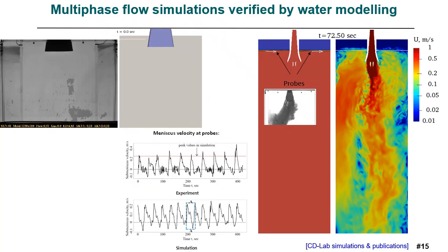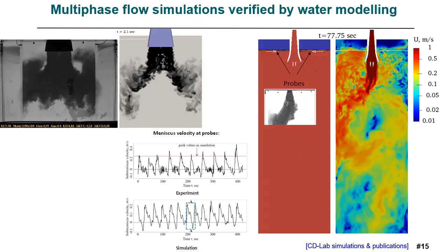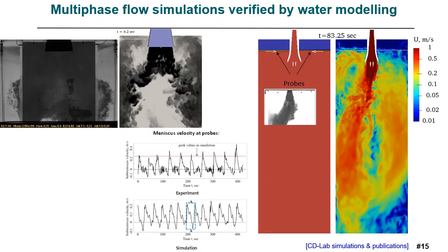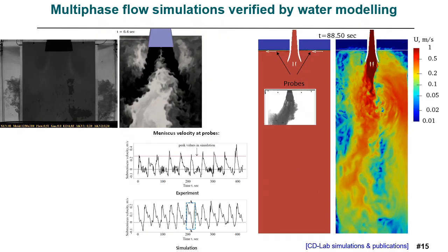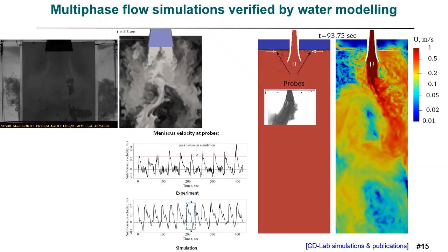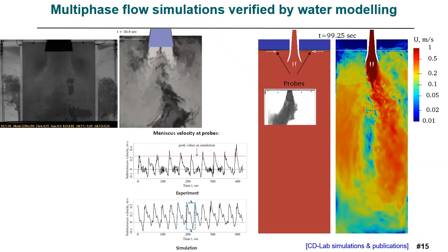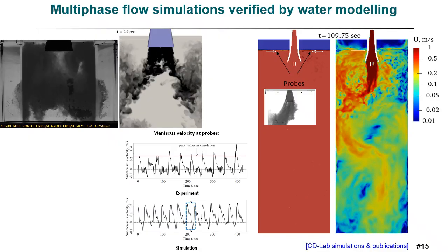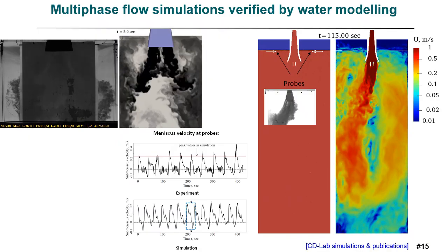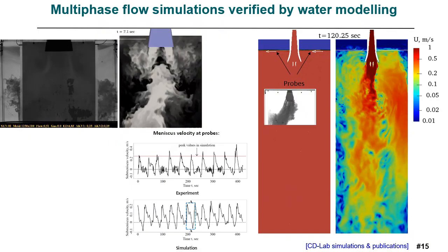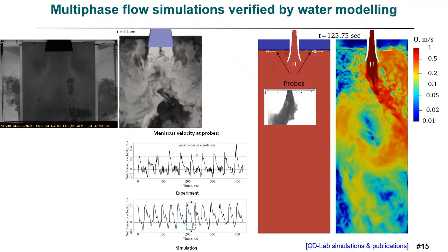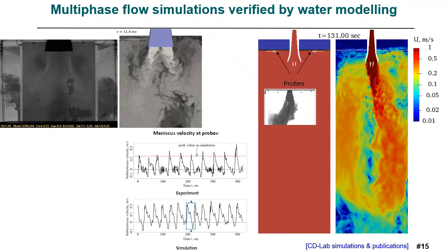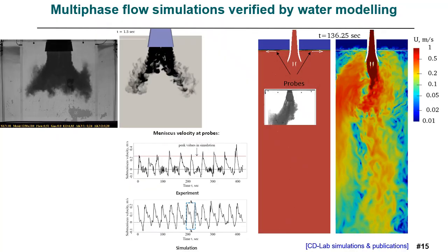However, we also tune our models to resolve such non-trivial cases as formation of the single oscillating jet in the four-port nozzle. Thereby, we verify mesh resolution and modeling technique in respect of the subgrid models, which can correctly resolve flow separations and flow oscillations.